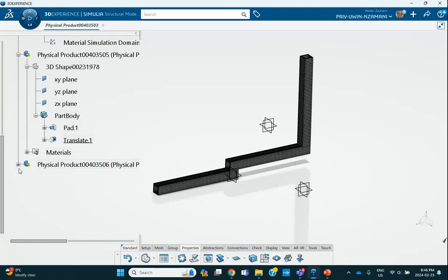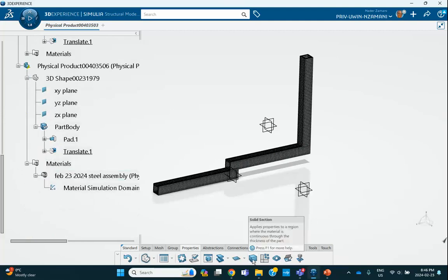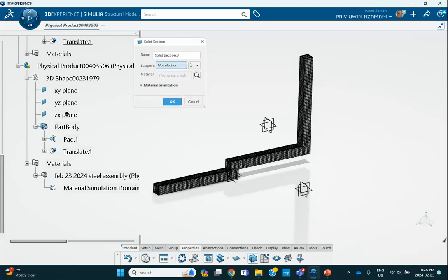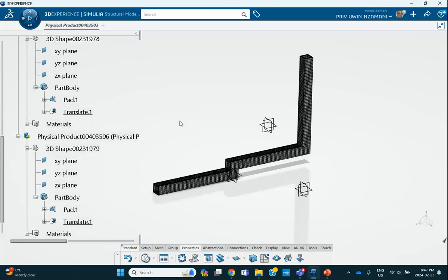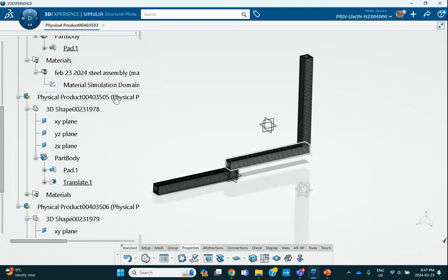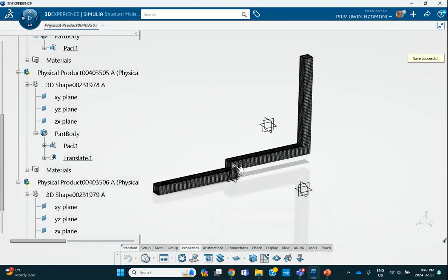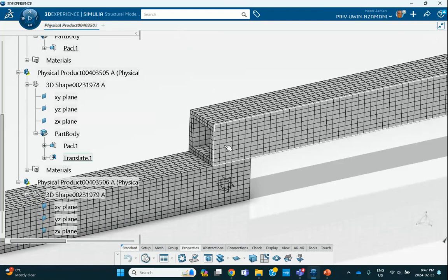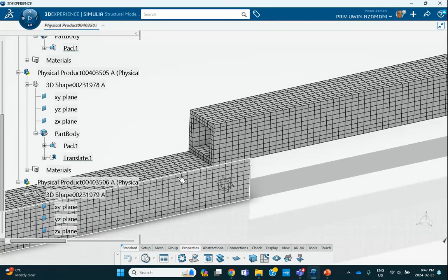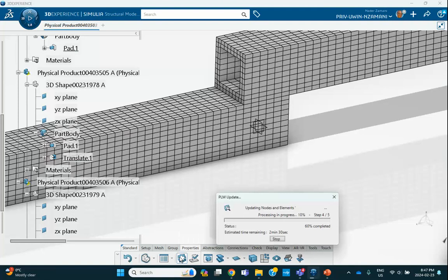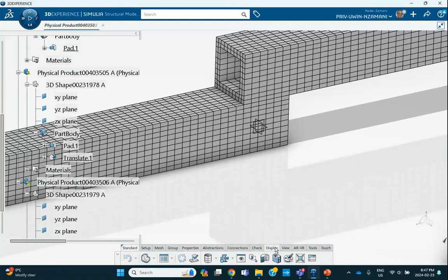And finally, for the last one, again, part body, where's the part body? Right here. If you select the mesh, it doesn't recognize, and you have to go and pick it from the database, but that's okay. So it's done. One last thing, I mentioned in tutorial 15 that there are multiple nodes at these locations. For example, let's check it out. First of all, let me update. And then we go to display, click on the numbering visualization.